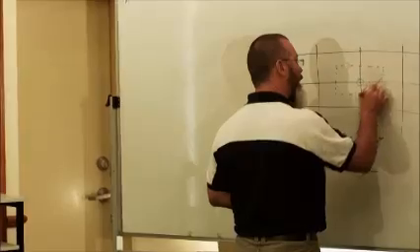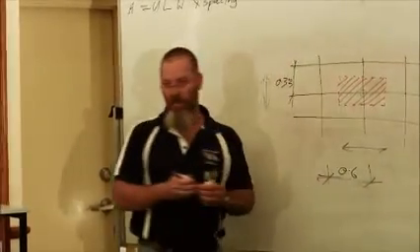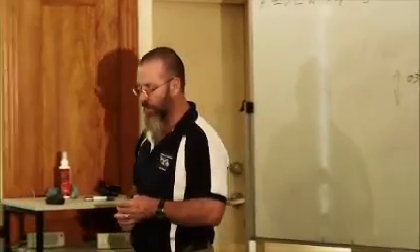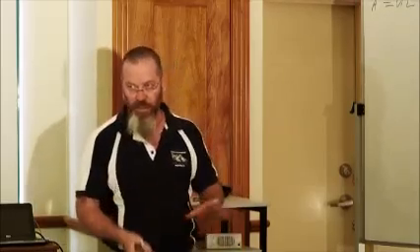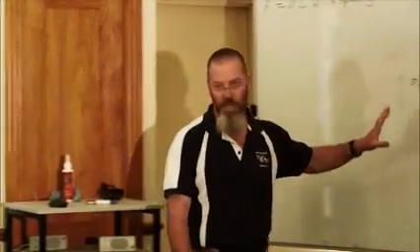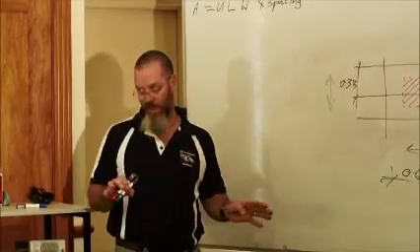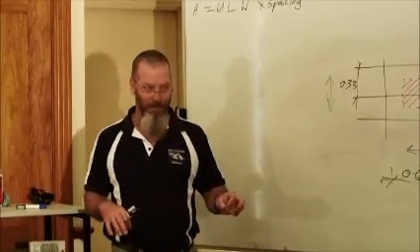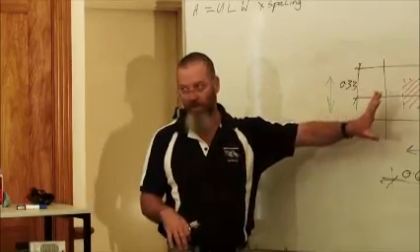So that shaded area there is the tributary area of that batten connection. What part, or the area, is contributing to suction or uplift on that connection? That's it there. You can actually do it mathematically, but I'd encourage you to do that drawing first, or that sketch first. You'll see there, my drawing skills are not great, crappy in other words, but I've just done a single line sketch.